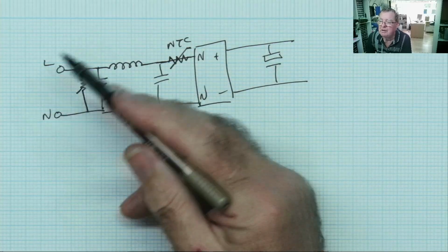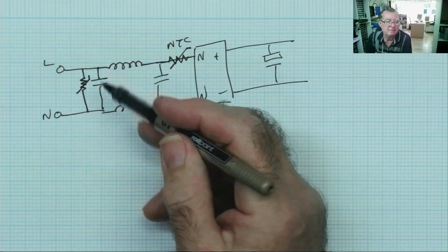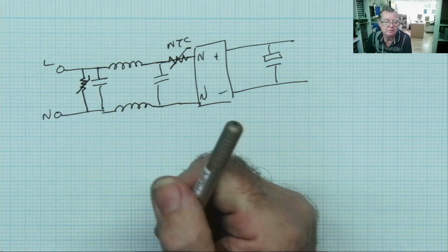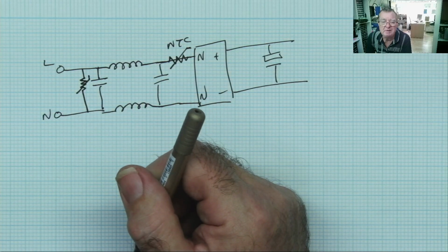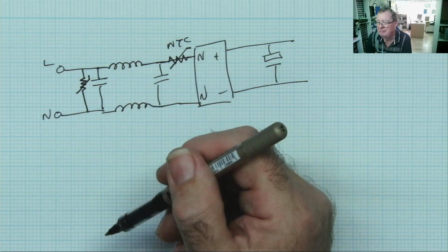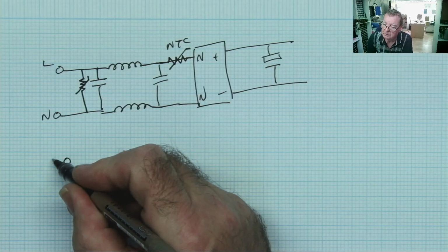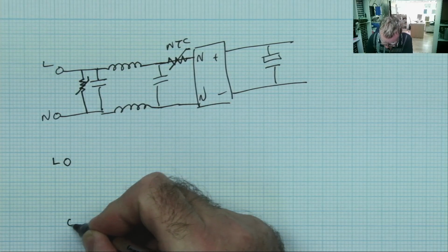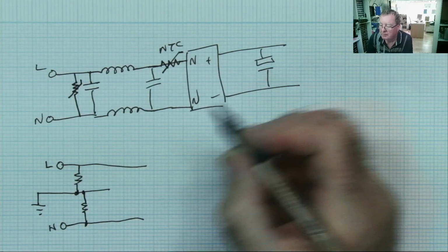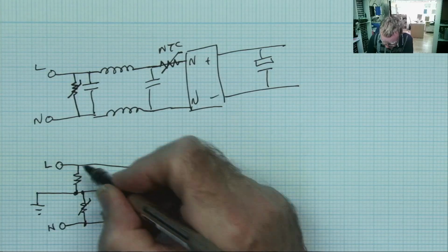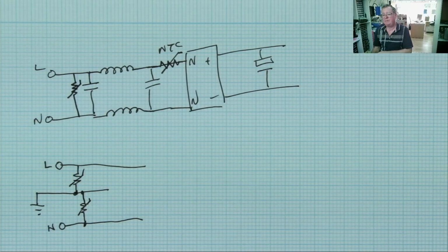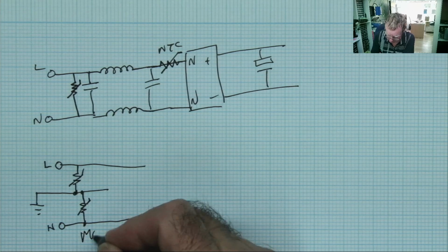But you can generally work out, or just ask around on the internet, on forums, what value you should put in there, okay? Normally they just sort of split open so you can actually read the marking anyway. Sometimes you might find something like this as well, that type of arrangement with two of them. Okay, so those are the MOV.